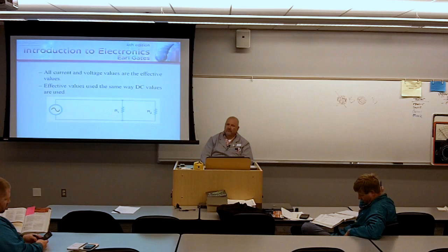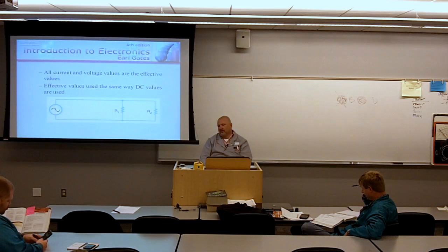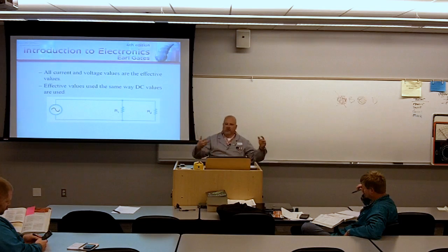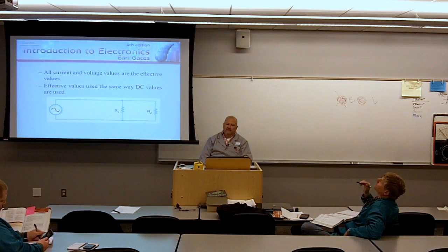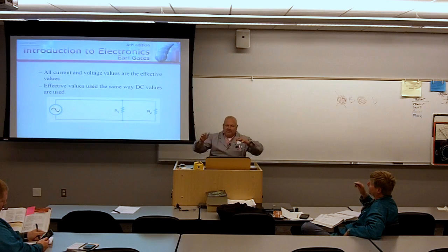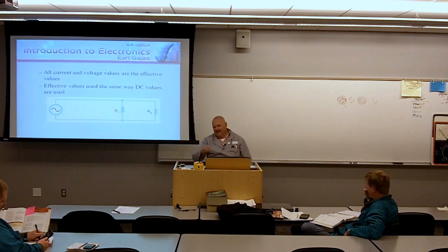On fishing boats and workboats, I've seen they start up the gen sets and then they're phasing, synchronizing with shore power? Yeah, you want to be able to synchronize your generator with shore power so you can transition easily from shore power to internal power, and that's kind of critical the way boats are. In aviation, it's not that critical. You plug into a ground unit, and then the lights all go off, and ding, and then you're on the ground connection.